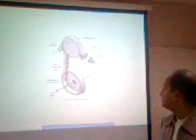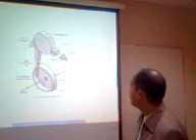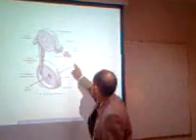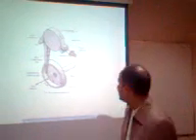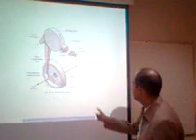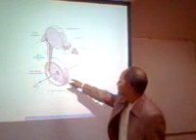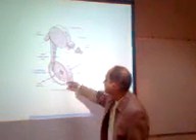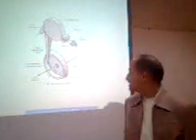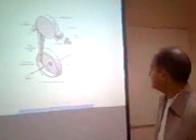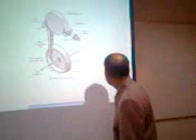This is the image of the rotor spinning machine. In the rotor spinning process, we have a combing roller. Here is the feed material. This combing or opening roller opens the material and throws the material into the groove of the rotor. The rotor is rotating. This rotation gives the centrifugal force, which accumulates the material in the rotor groove and twists it as well and makes it into yarn.